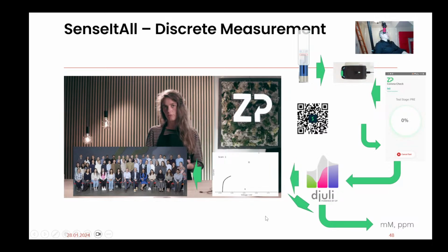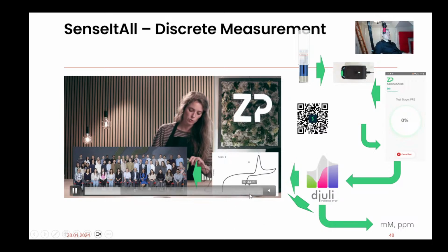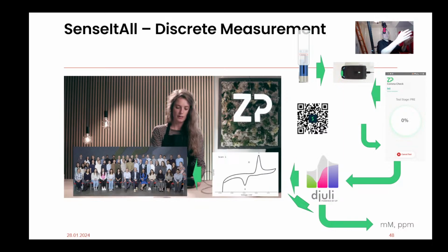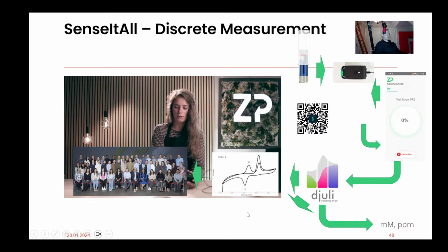So my suggestion to these people is, don't do that perpendicular design. We can't do the electrodes at a low enough price that makes that attractive to you. We can make those hypervalue carbon electrodes at a low price and low volume that's attractive to you. And I think it makes for a better product, because I make electrical connection at one end, you add the sample at the other end, so that keeps the electrical connection and the sample well away from one another. It makes for quite a narrow strip, which we can put in tubes and pack really tightly in boxes. So I would definitely go for that particular design.